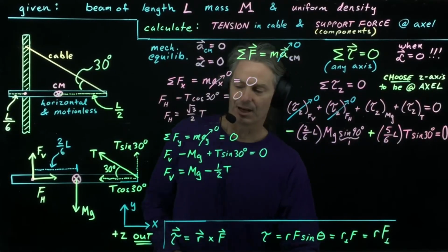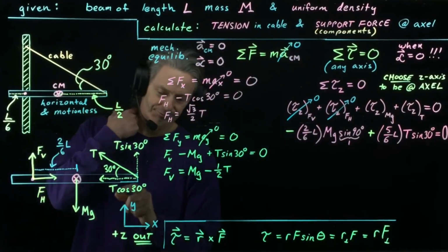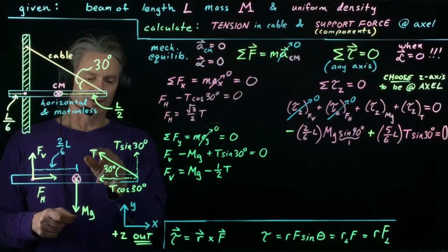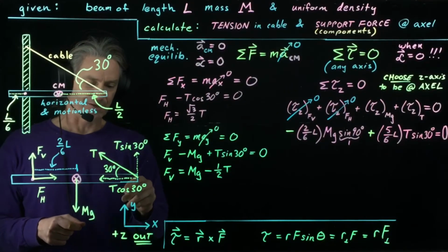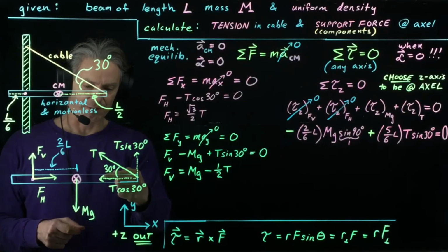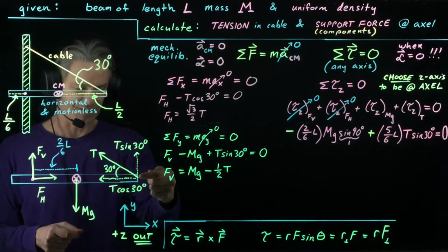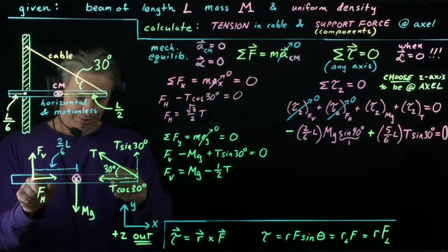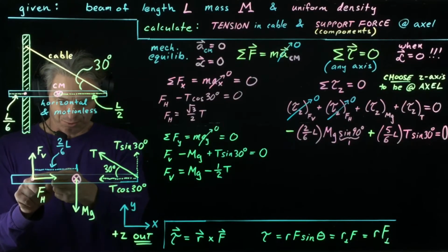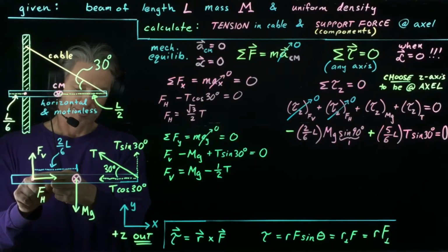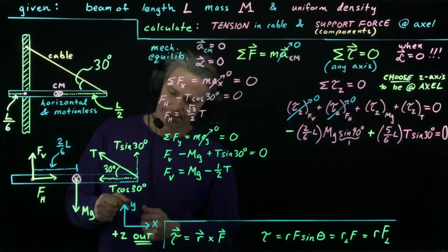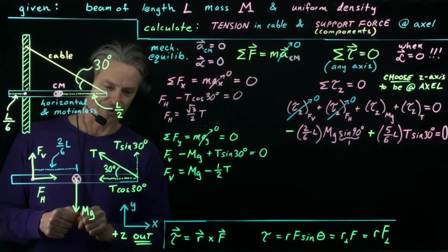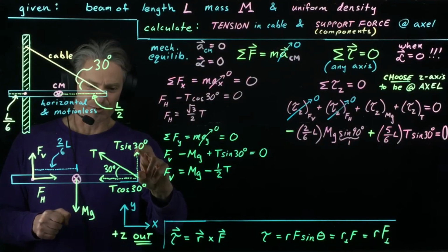All right. I could have done this a different way. We could note that this tension force has two components. I've got this component, which will produce no torque, because the line of action of this force component passes right through our chosen z-axis. All right, so this will produce no torque. Only this part will produce a torque.